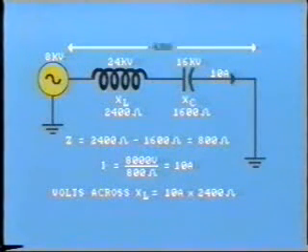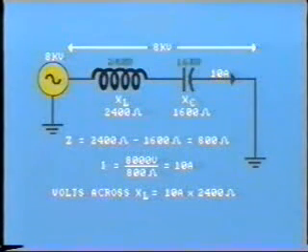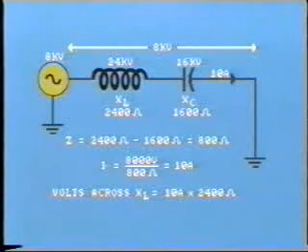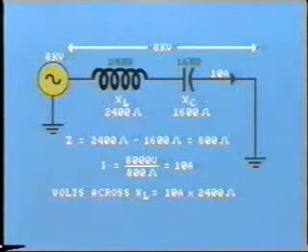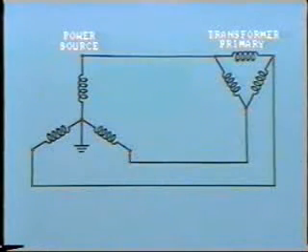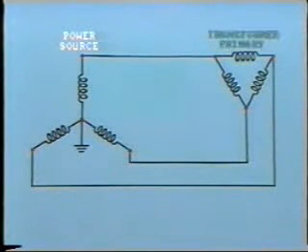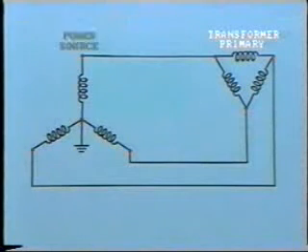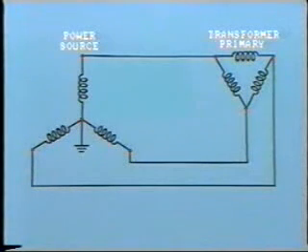So although only 8 kV is applied across the total circuit, we have very high voltages in individual parts of the circuit. And this is precisely what happens when we have ferroresonance in the power system. Typically, this can occur where we have a delta-connected primary of a distribution transformer. In this system, the distribution line is being fed from a Y-connected secondary with the neutral grounded.